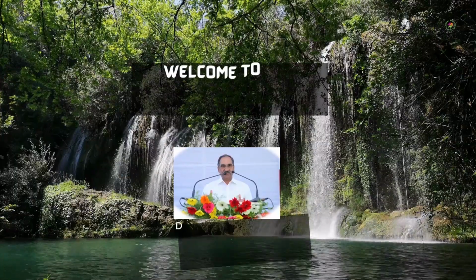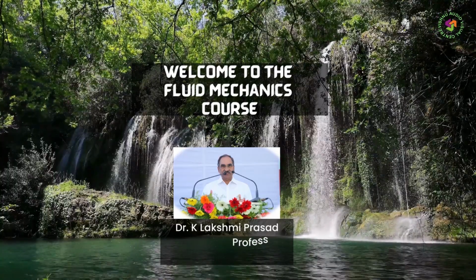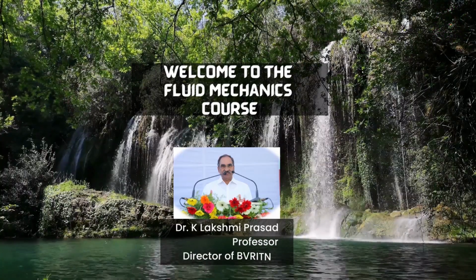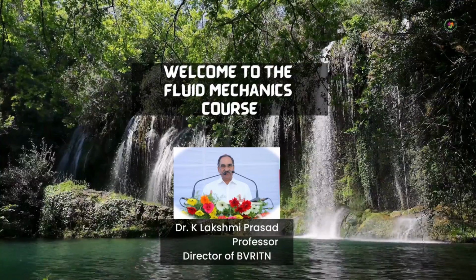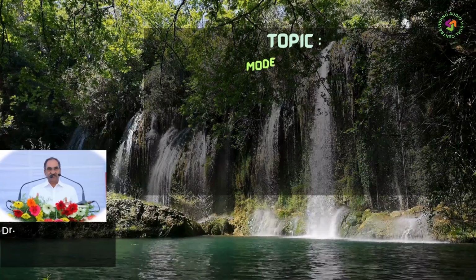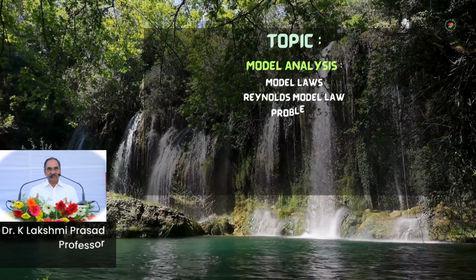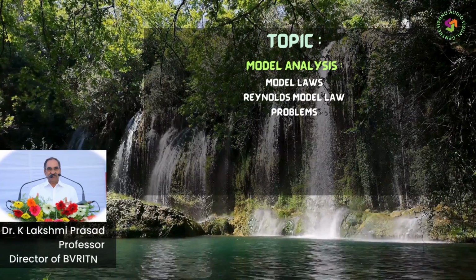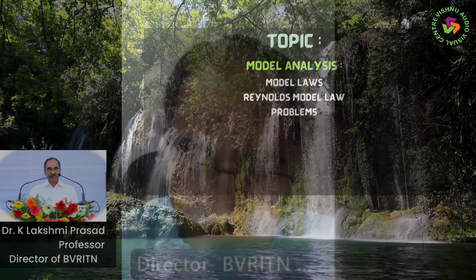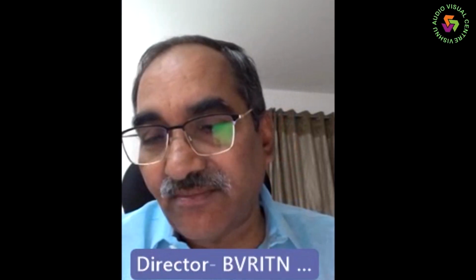Good evening, everybody. In the previous lecture, we discussed dynamic similarity and mentioned that dynamic similarity is similarity of forces. Six forces we have considered, and at the corresponding points, the ratios of these forces should be equal, not only in magnitude; the direction in the prototype and model should also be the same.